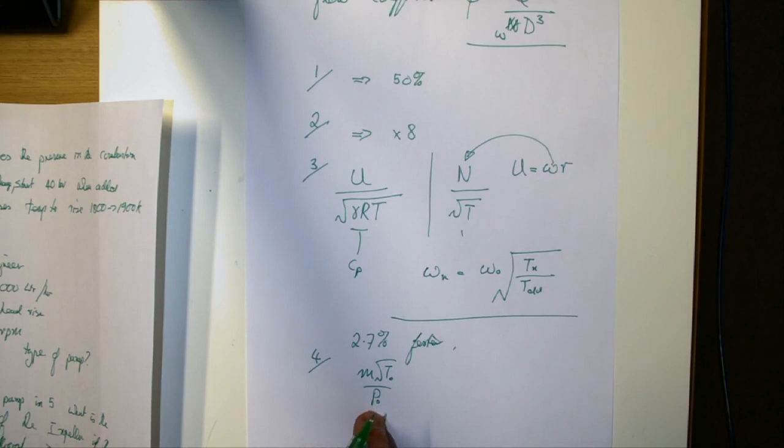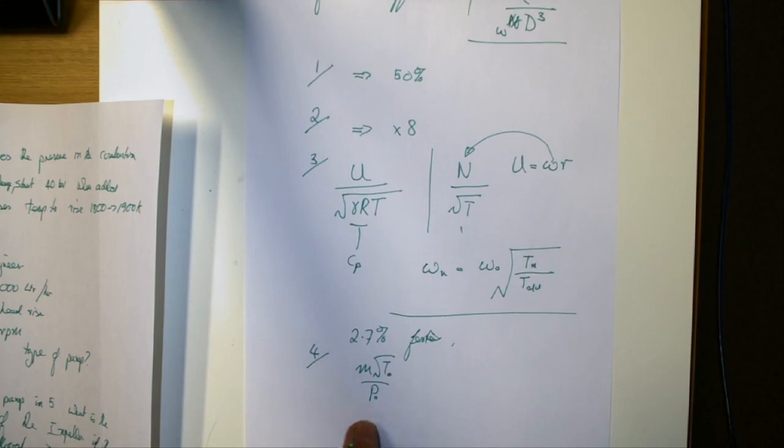I'm telling you that the temperature is going to increase from 1800 to 1900. The mass flow can change, but it takes time for the mass flow to change, because the mass flow is determined by what the compressor has been doing. So instantaneously, when you put in more fuel, the mass flow stays the same. In fact, it actually goes up a bit because of the fuel you've added, which has mass. But that is a 1% adjustment, so not worth worrying about at this stage.